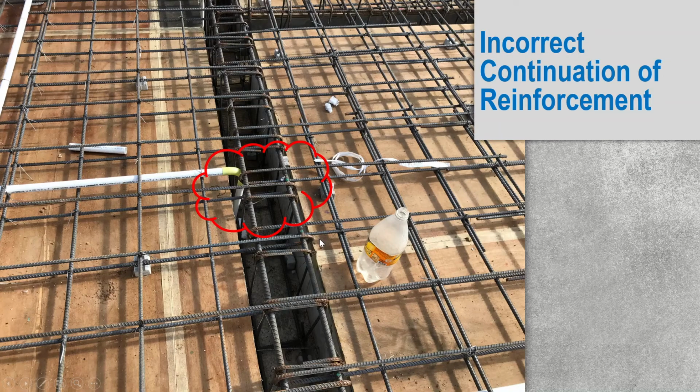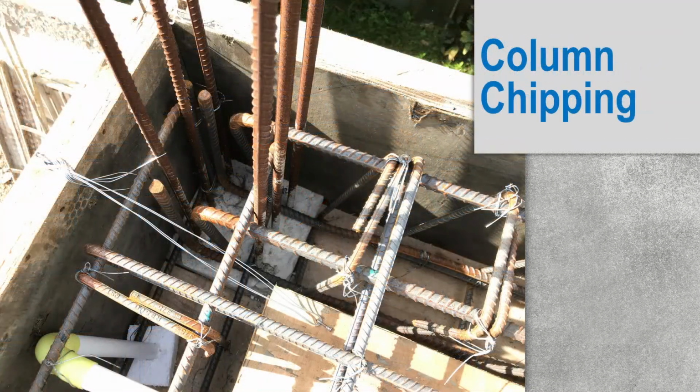Here you can see a continuous slab. In this continuous slab, you can see two U-bars are provided. Is this required? No. You don't need to provide the U-bars there, because since this is at the same level, you can continue this bar like this. You can put the reinforcement bar continuously. You need not provide U-bars like this. This is also a kind of construction error made by the contractor.